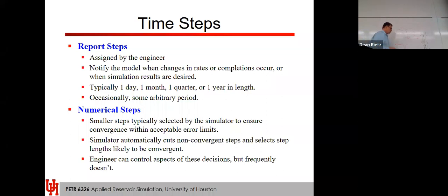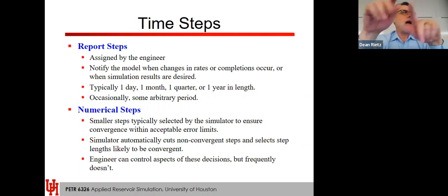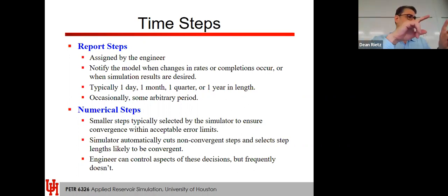Okay. So just a general rule of thumb is if your model is having convergence problems, the first thing I would do is impose a time step limit. You don't have to change anything else in your model. All you do is put a keyword in there and say what the max T-step is. And usually it's a small one. Usually you start the model with a T-step keyword, so it'll start off with like a 0.1 day, just to get it going. And then the next one might be the maximum time step. And then the next one might be the maximum cut or something like this. You have to look at the manual for that. But what I'm saying is if you have a model that is having convergence problems, the fastest and easiest thing to do is put that one keyword in there and limit the time.